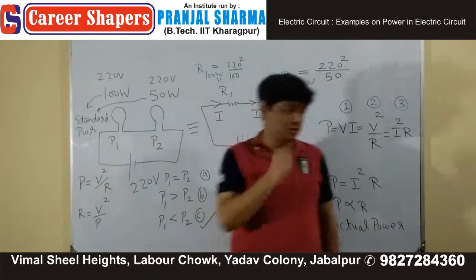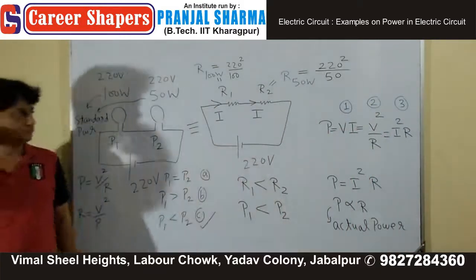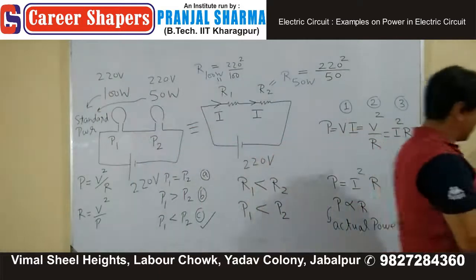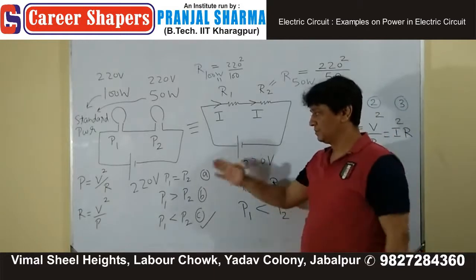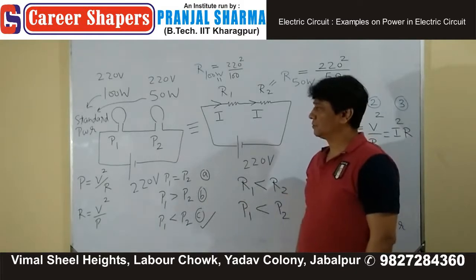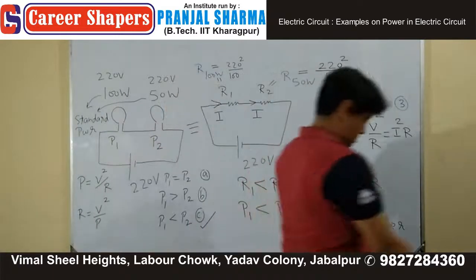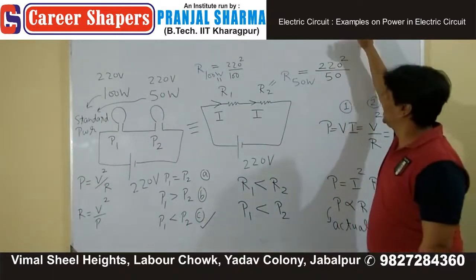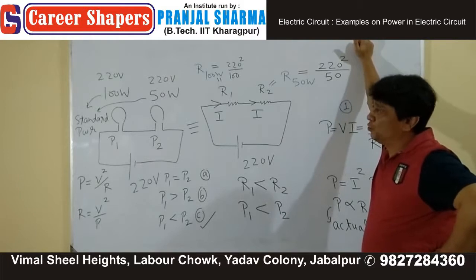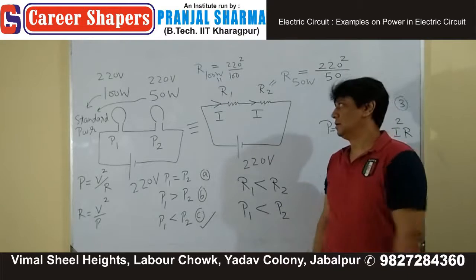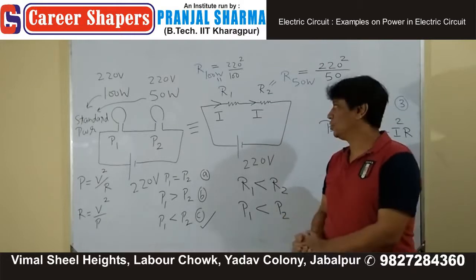Since none of you could answer it, write this down also as a statement. Although both bulbs are connected to a 220 volt supply, since they are in series, this 220 volt will be shared by both bulbs.